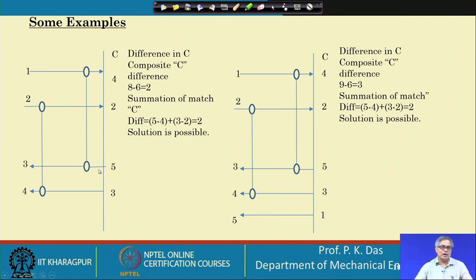This is also one condition to be satisfied. And here the number of hot streams is less than the number of cold streams, which is also desirable for the hot end of the pinch point. Similarly, we can proceed to the next slide.